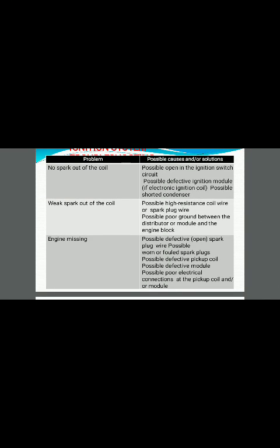If there is no spark out of the coil when the whole system is turned on, what are the possible solutions? A possible open in the ignition switch circuit.